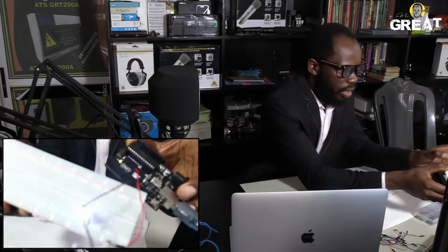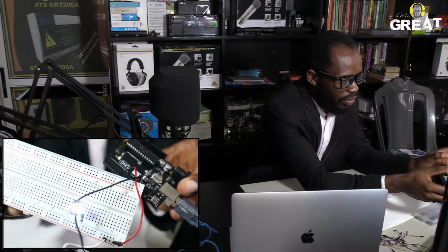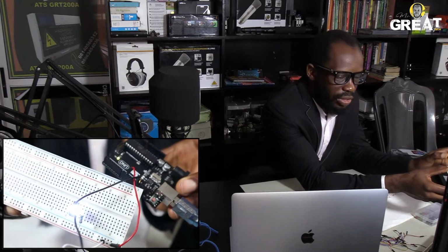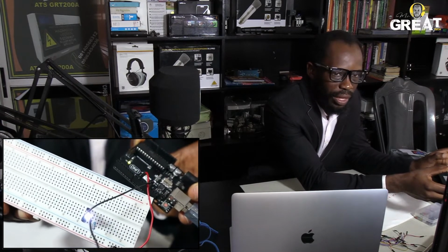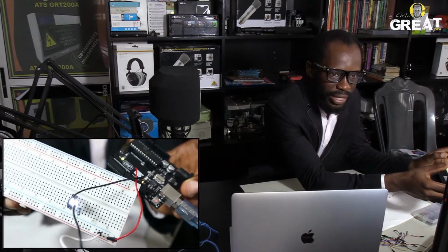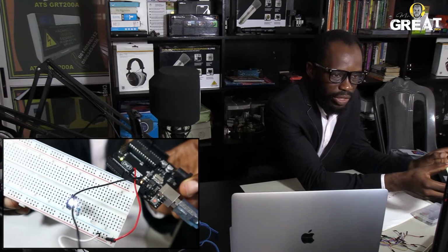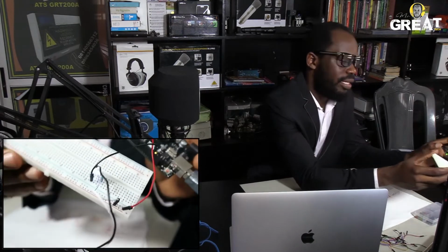When you look at the LED very well, you can see it didn't go off completely. So at that point, the voltage is not all that 5 volts again. When it is off completely, it will be 0 volts. But you can see now there's a delay in between the high and the middle voltage. Understand? So that is what we are going to achieve today in our analog write command. Let's go and see the program, how we can achieve that.